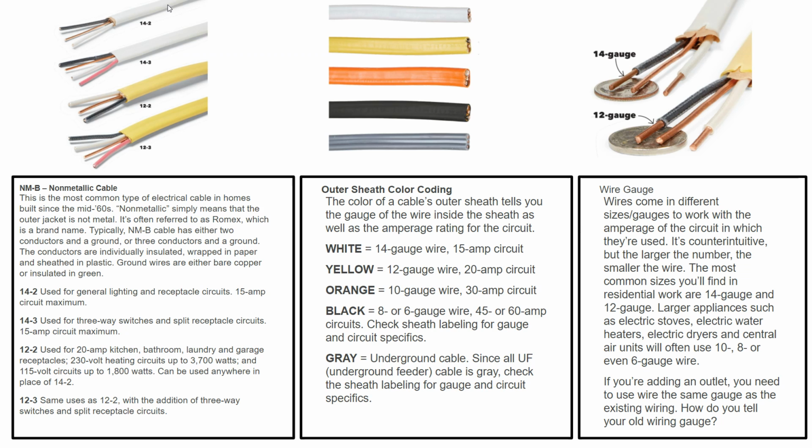Now you might wonder why, and you probably do, why do we have that? Well, depending on the light switch or the circuit, you might need to have this extra conductor. This is your standard. The 2-wire setup is what you normally will see. And this is our hot, which is black, and our neutral, which is white.